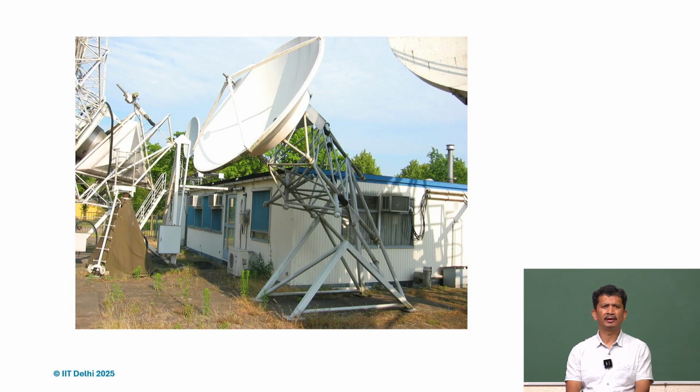Even in many air bearing stages, to eliminate certain over-constraint, leaf springs or sheet flexures are used, but those have a thickness of the order of millimeters. On the other hand, for some MEMS devices, it can be in microns. The principles and the way it works are the same; only the scale is different.